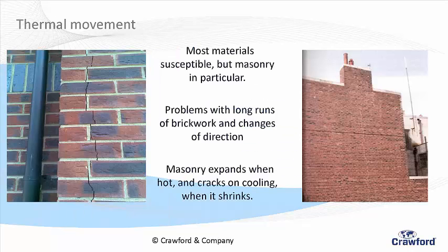Thermal movements. If I said to you all materials expand and contract, some more than others. If they expand and contract more than they're designed to, they crack. It's natural, it's fine, and it's designed for in a lot of cases. So you get a design movement. Here's one, typically, that's usually vertical. It's even in height. You can see it's not rotational. And this one is at a corner of a building where two lengths of wall might expand, and it pushes the corner out, which is what's happened there.